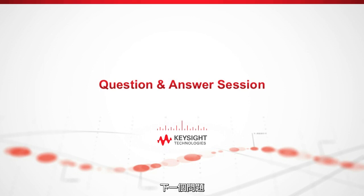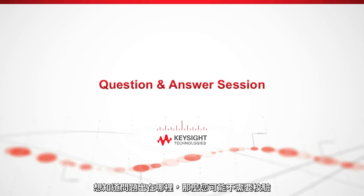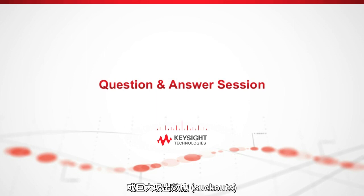Okay. Next question: I currently perform multi-port calibrations on my system. How often do I have to recalibrate? The old question pops up again. Well, it's a personal preference, really, and it depends on what you're doing with the data. If you're just troubleshooting and learning where the problems or failures are, you may not need to calibrate. You're looking for qualitative data, for big reflections or huge suckouts in the frequency domain.